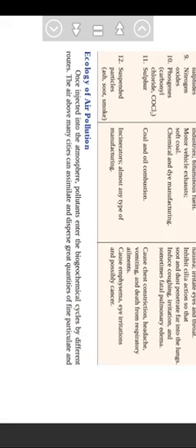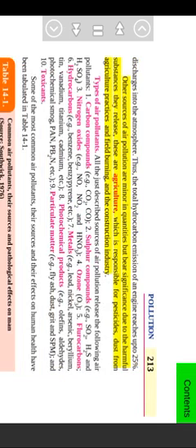The evaporation through the carburetor occurs when the engine is stopped and heat builds up; as much as 12 to 40 milliliters of fuel is lost during each long stop. Petrol and diesel exhaust emits hydrocarbons, carbon monoxide, oxides of nitrogen, some gas particulates, and other gases. Vapor escapes between the walls and the piston, figure 14.1. Hydrocarbons and other particulate and gaseous emissions enter the crankcase and are then discharged from the automobile into the atmosphere. Thus, the total hydrocarbon emission of an engine reaches up to 25%.